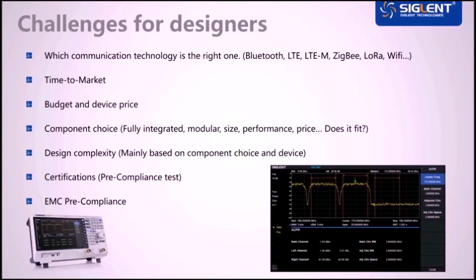Because we are talking about billions of different solutions for at least a similar amount of applications, I would like first to go roughly through the decision-making process that decides what you will design later. Because what you want and should test is mainly based on these decisions. First, we have to decide on a communication standard. If you want to integrate your device into a smart home, then choose Zigbee or Z-Wave. If your device has to work anywhere in the world, it might be LTE or Extended Coverage GSM for IoT devices. There's also a fair chance that your device needs multiple interfaces.